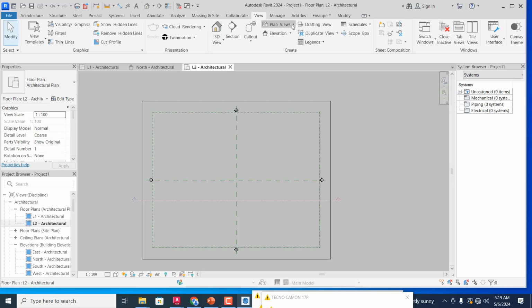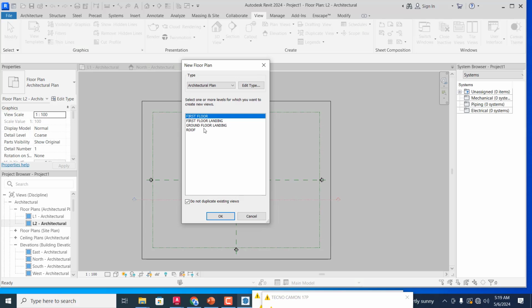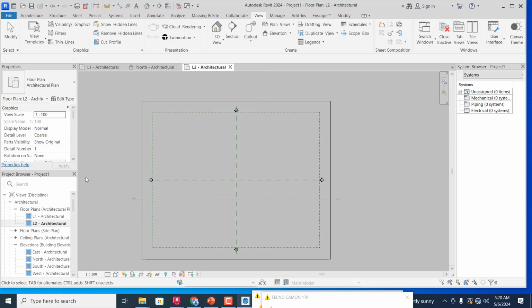So when you come under your view trying to include your ground floor, ground level and your ground floor level, it will most likely not show here. So it is important that you delete that, because if you come down here at the left hand corner of this screen under your project browser, you will see that all those other levels which are supposed to appear here are not showing. Okay, so you can see this is the levels based on default settings that are showing here.